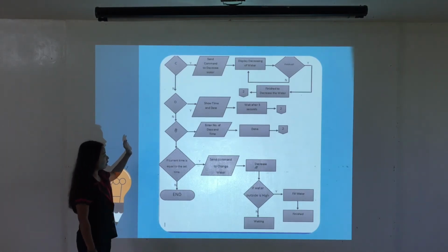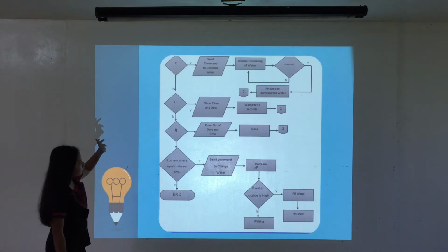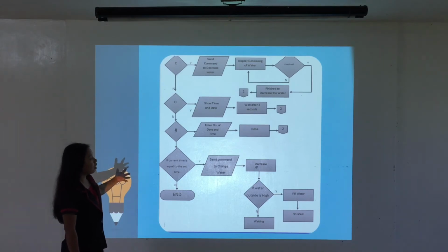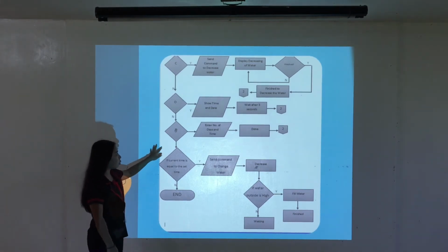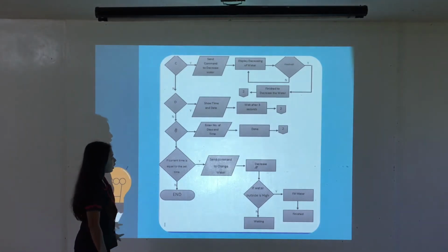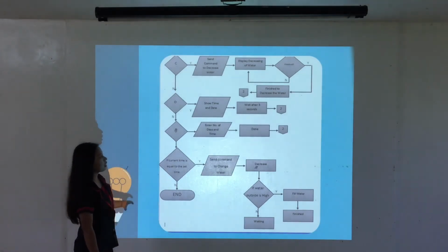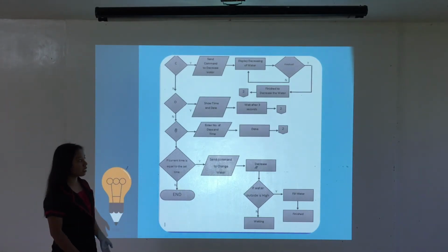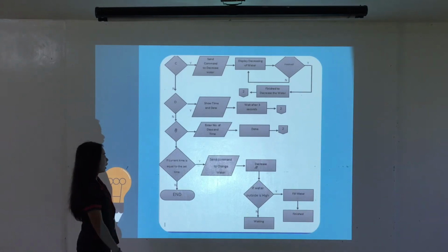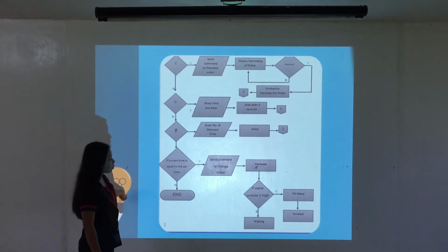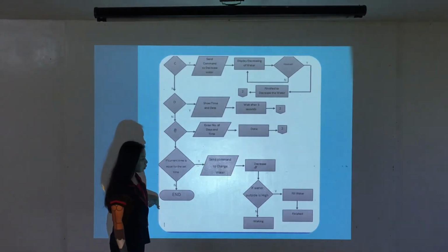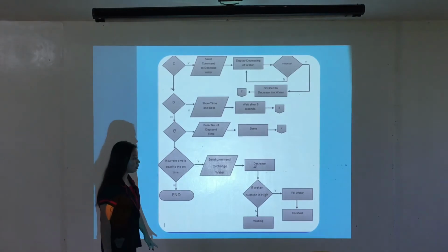And if button D is pressed, it will show the time and date, wait for 3 seconds, and go back to the select operation section. If the 0 button is pressed, enter the number of days and time, and when done, it will go back to select operation while waiting for the set date and time of changing the water. If the current time is equal to the set time, it will send a command to change the water and will decrease. If the water outside is high, it will fill the water, else it will wait.